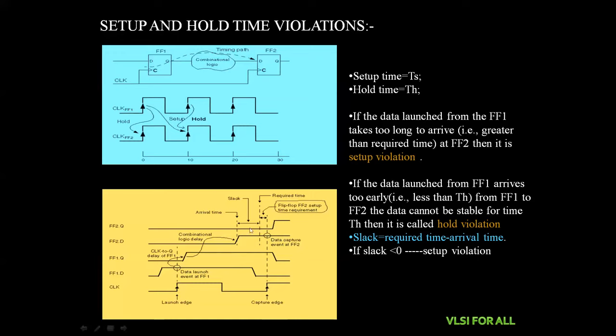So we need to have a stable data signal before a certain amount of time from the occurrence of the clock signal. So here the signal is stable, so we are not going to face any setup time issues. So let's check for the hold time violation.